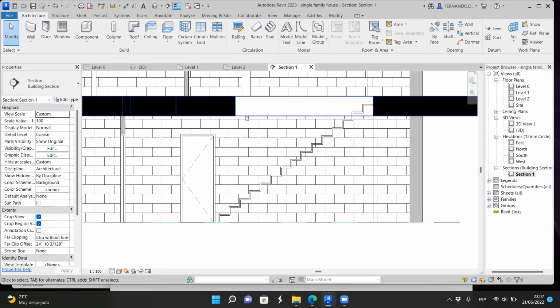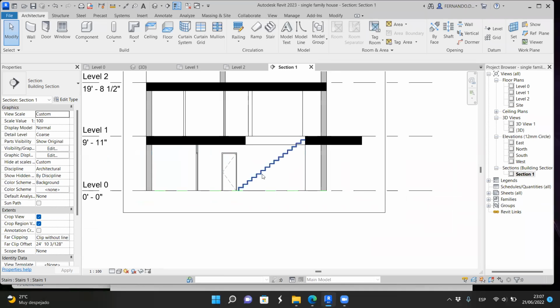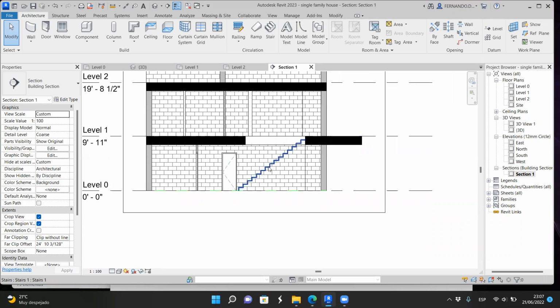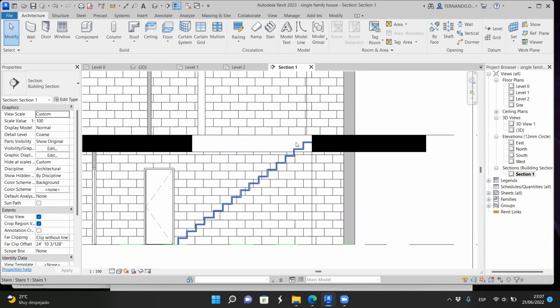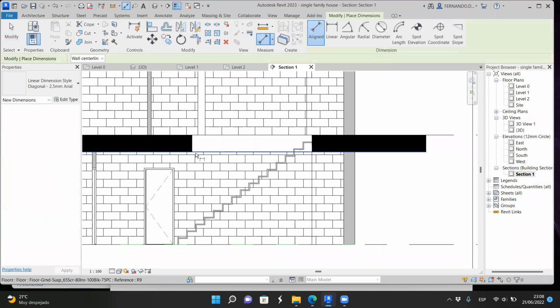Okay, so that's why I can't make this void any smaller, because I can hit my head on that slab. So when we're designing staircases, we have to design a plan, and then we have to check the section that there's enough distance. And what's the distance? Well, the distance between this point and this point has to be more than 7 feet, probably 8, between this and this.